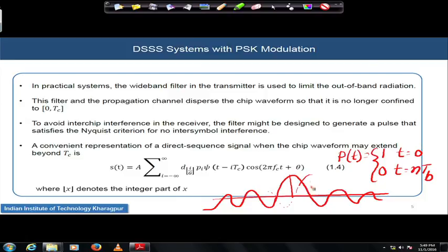So, you are getting a peak value when the others, its corresponding pulses, are not having any peak. The pulse that Nyquist took has places where it is minus TB and this is plus TB. So, this is twice the TB value, this is minus twice TB value, and TB is equal to 1 by RB, we will call the bit rate RB.